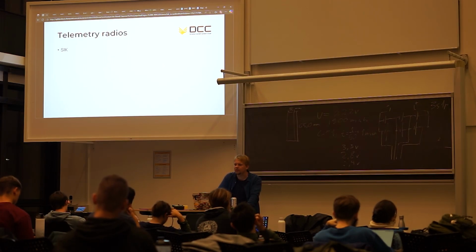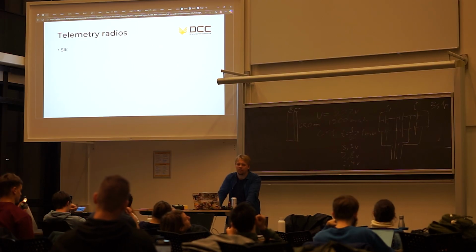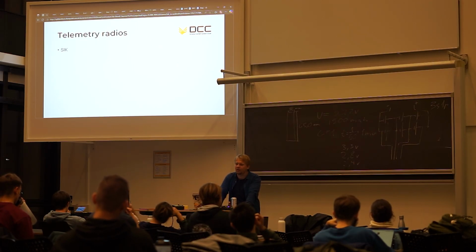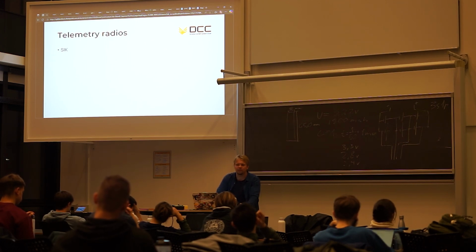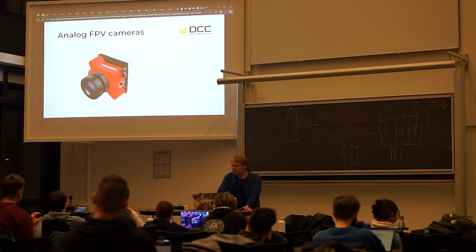They are very useful because some of the calibration on the drones needs to be done with the drone pretty much being flight ready. You're going to have a computer right next to it. You can't do a magnetometer calibration, the computer's going to throw it off quite a lot. Also, you need to move the drone around for accelerometer data, and it's all just nice to be able to fully communicate with an autonomous drone without a wire. So that's why you have telemetry radios. Now, FPV stuff.